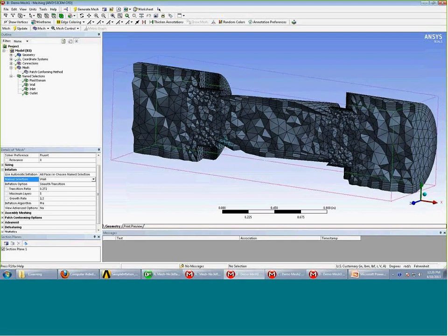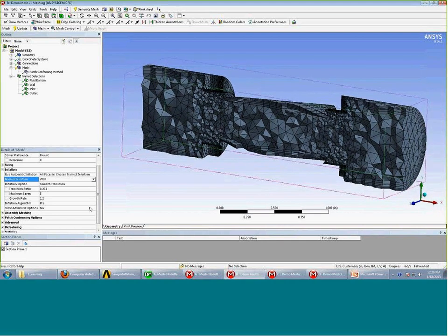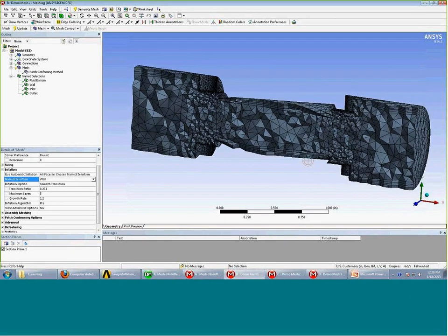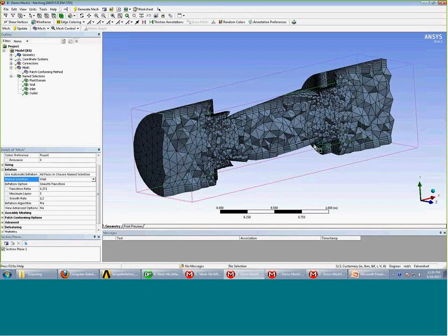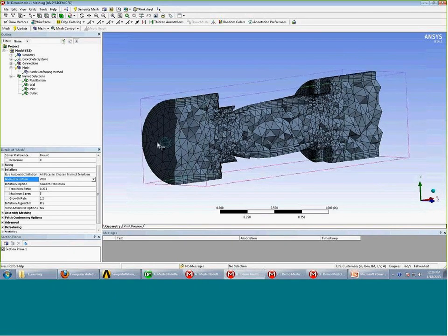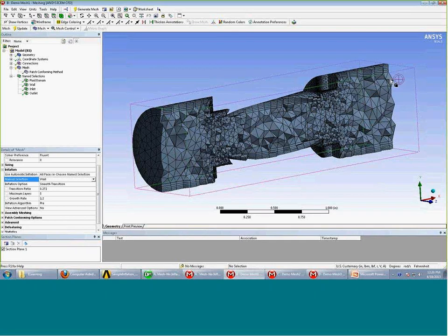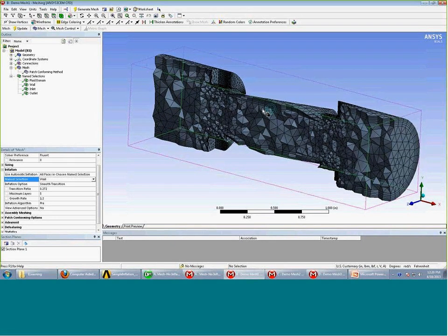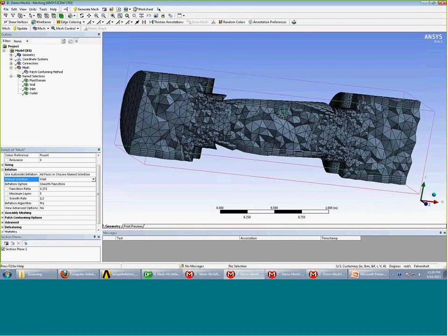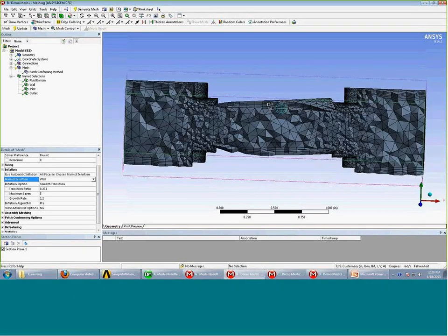And as you know, with the rest of the parameters remaining the same, if I were to regenerate the mesh, it will look exactly like this. So these two ways I can control where exactly I want to generate the mesh on this given part. Note that when I put both my cylinders back in, these surfaces automatically will be ignored because they are contact regions. Right now, since we suppressed them, this part only has a single body.